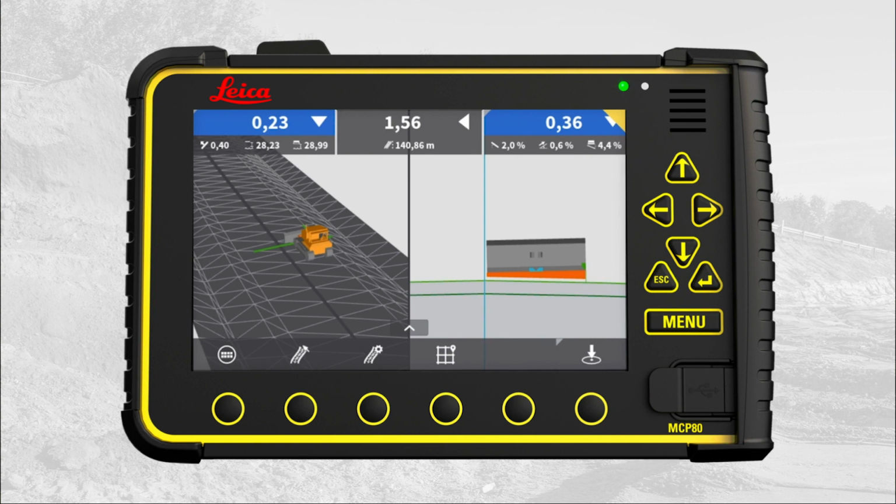The top bar shows cut fill value of left corner blade, side distance to selected line, cut fill value of right corner blade. The lower bar shows actual offset and offset type, design elevation under the tool point, actual elevation of the tool point, stationing, design cross slope, design long slope, actual cross slope on the cutting edge. Note: stationing is only available in 3D run screens.